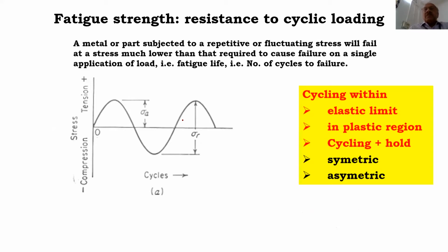So that represents high cycle fatigue. Or it can be in the plastic region. You are deforming the material between tensile and compressive modes, and the strain corresponds to the plastic strain.